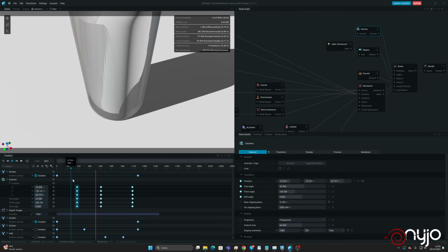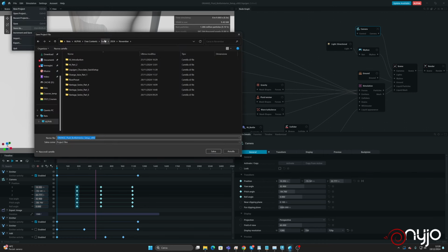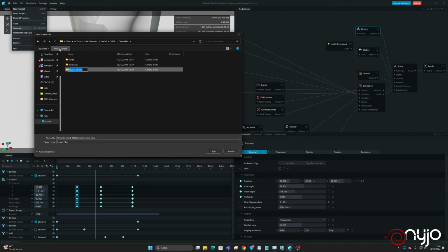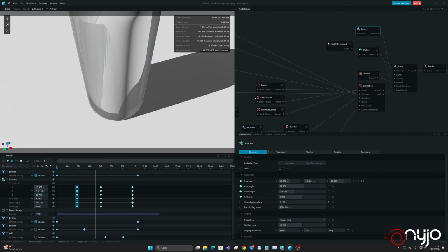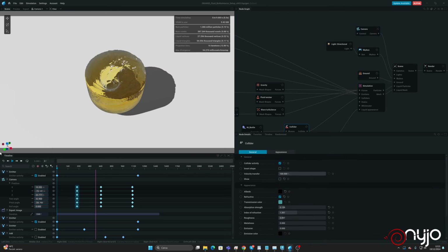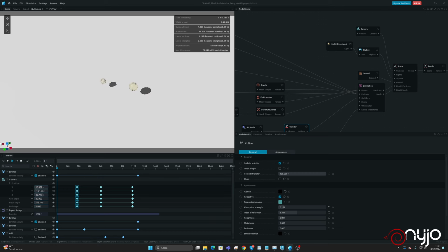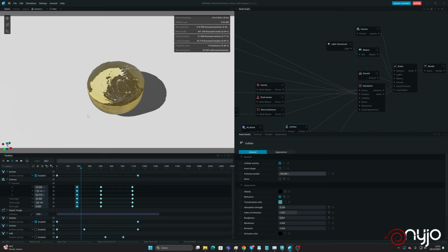I think that for our purpose that's okay. So we go to save the scene. This one is for December. New folder, orange juice part 2, a new scenes, and here we say that this one is the number 3. So again, this one can be not visible, and back with the R key or using directly the button, and then press space to see the simulation.